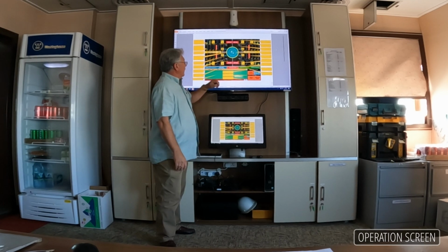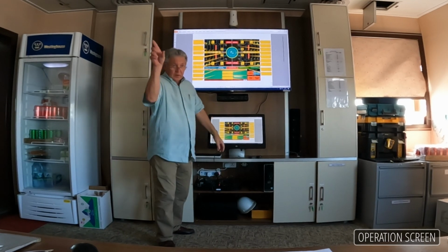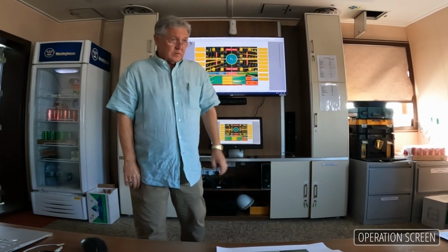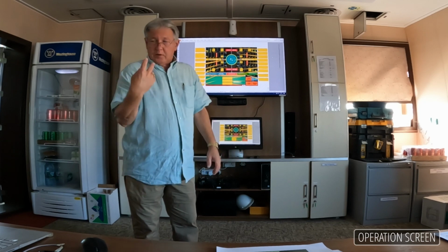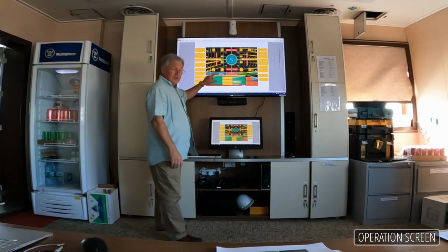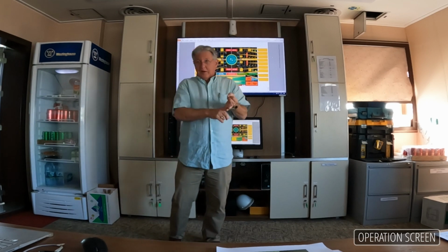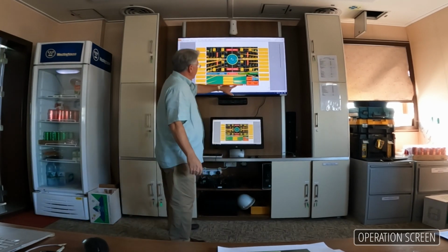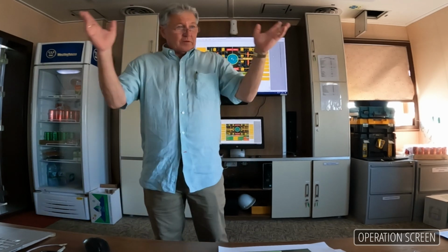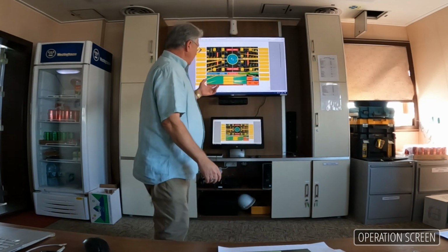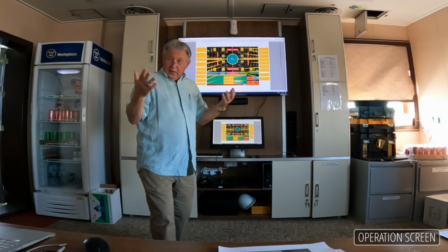Anytime there's 3 letters in an alarm, they disappear from the screen for you. So now you got, say, circuit breaker. It's a C, but you do not acknowledge, you're busy, or whatever. And then someone fixed the circuit breaker, so now the alarm's not there. But we don't want you to miss it, so then it'll say CD, and think of it as coming and done. It's silly, but it's true, CD, okay? When you do acknowledge it, now it's a CDA, and it goes away. Because no one ever seems to notice. People call me sometimes, what's this C and the D and all this stuff? Well, that's how it works. So, for fun, C, coming, A, acknowledge, D, done.